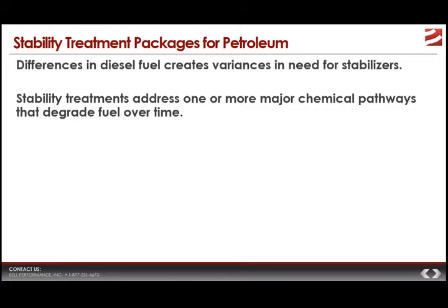So if you can't know that practically, well then, the best thing that you can do in making a decision is to make sure that whatever you choose has the best chance of being most effective in the most different kinds or different compositions of diesel fuel. So how do you do that? Well, a stabilizer or a stability treatment that's going to be effective is going to have to address at least one of the major chemical pathways or major chemical problems that arise when fuel's going unstable. Ideally, it will address all of them.